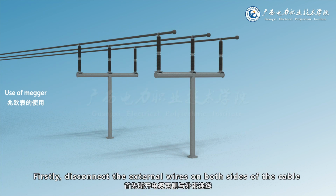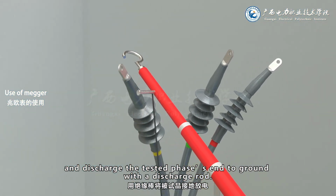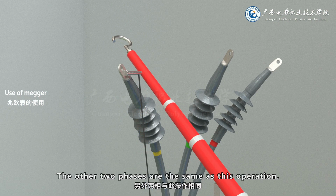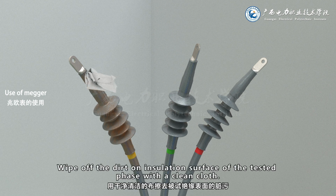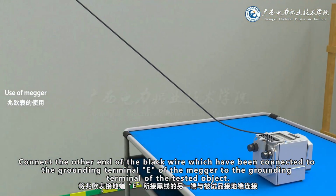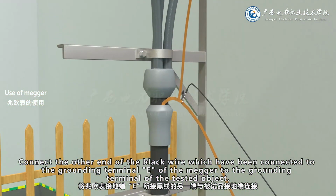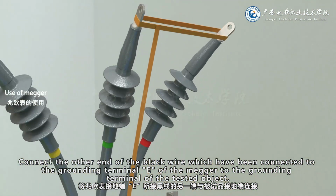Firstly, disconnect the external wires on both sides of the cable and discharge the tested phase's end to ground with a discharge rod. The other two phases are the same as this operation. Wipe off the dirt on the insulation surface of the tested phase with a clean cloth. Connect the other end of the black wire, which has been connected to the grounding terminal E of the Megger, to the grounding terminal of the tested object.